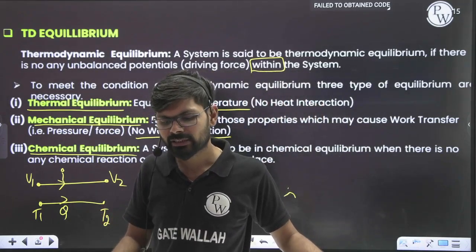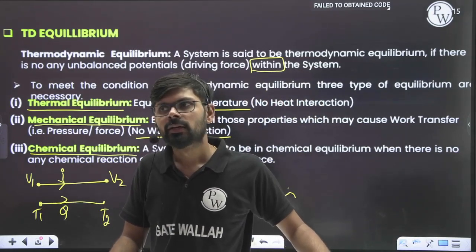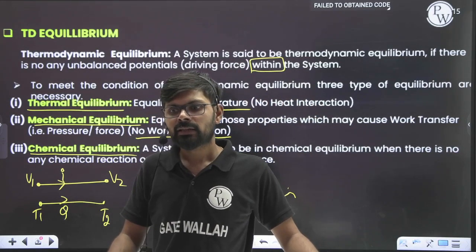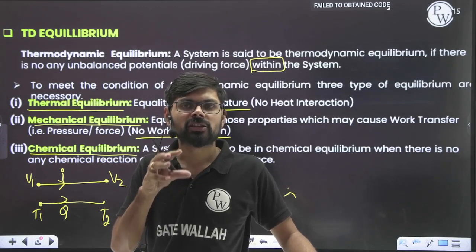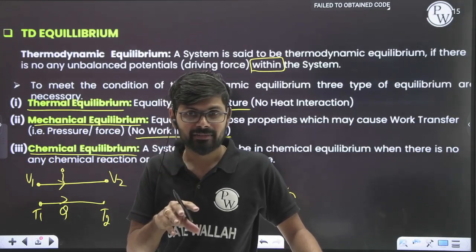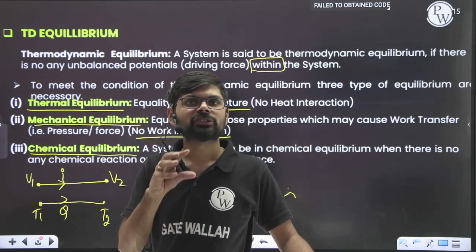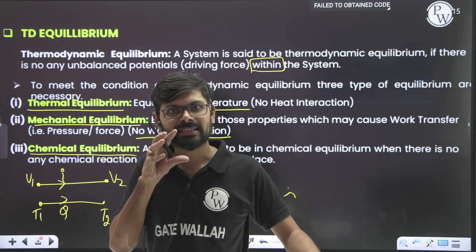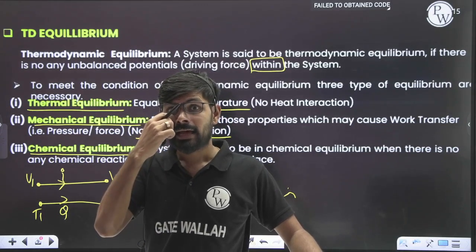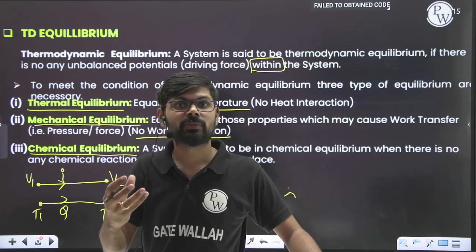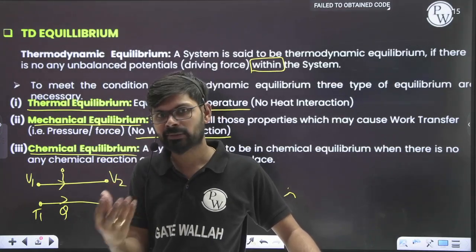What is that assumption? That assumption is very, very simple. The combustion phenomenon is not considered. Listen here carefully. The combustion phenomenon is not considered in the analysis, and the combustion is replaced by an equivalent amount of heat addition process.